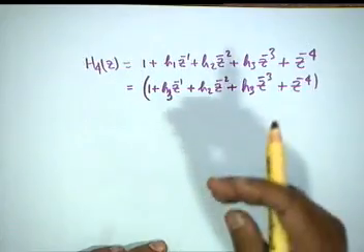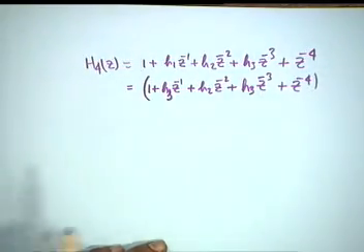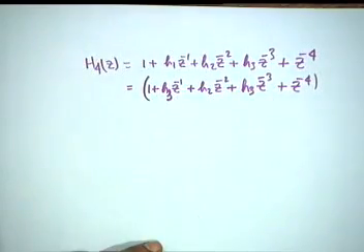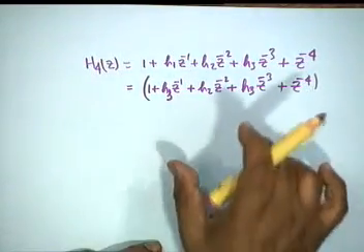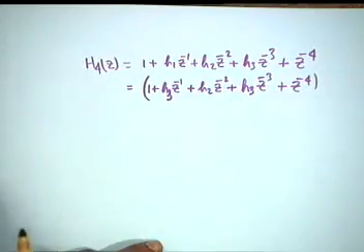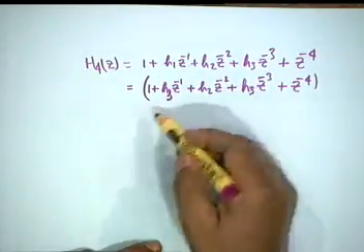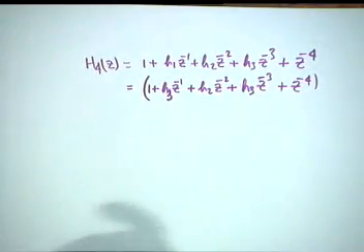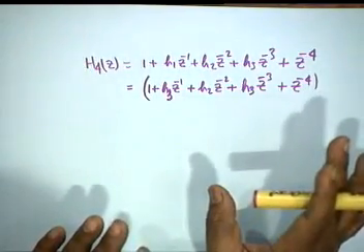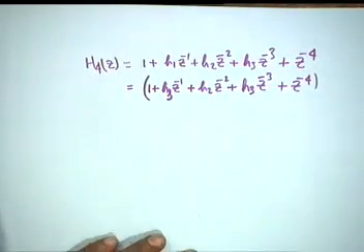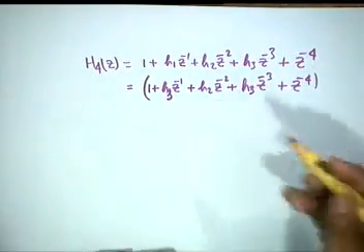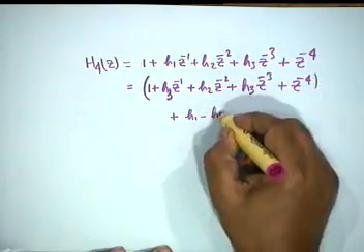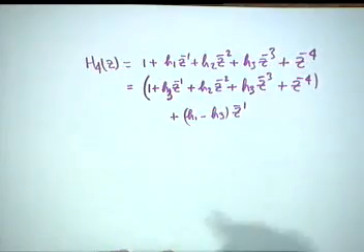In other words, the tap had to be after 3 delays, but then after 3 delays calculation becomes a little bit more involved, and therefore to reduce the calculational effort, we bring the higher power coefficient here. Do you understand the difference? It will work in both cases. No increase in complexity, no increase in number of multipliers, but to find that coefficient would be a little problem. It is much easier here. Then we have to subtract, we have to use H1 minus H3 Z inverse.